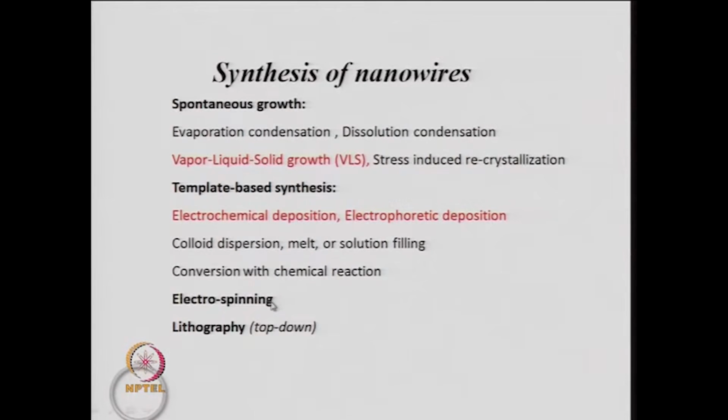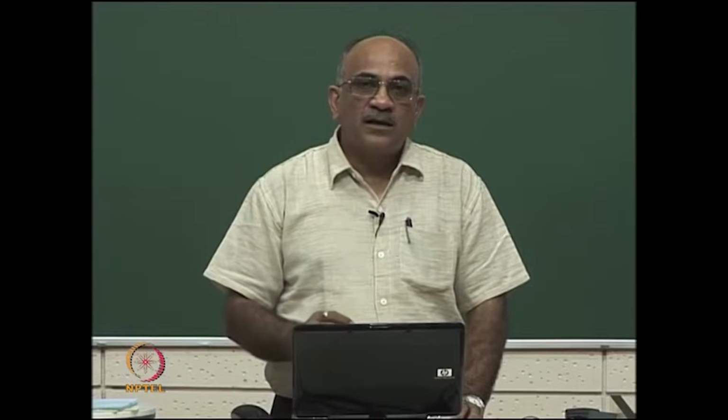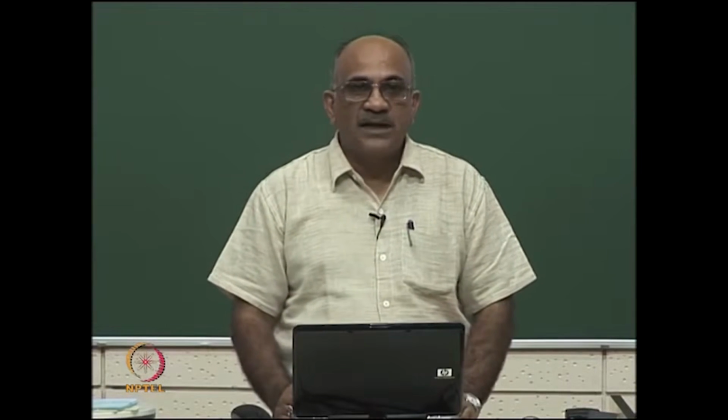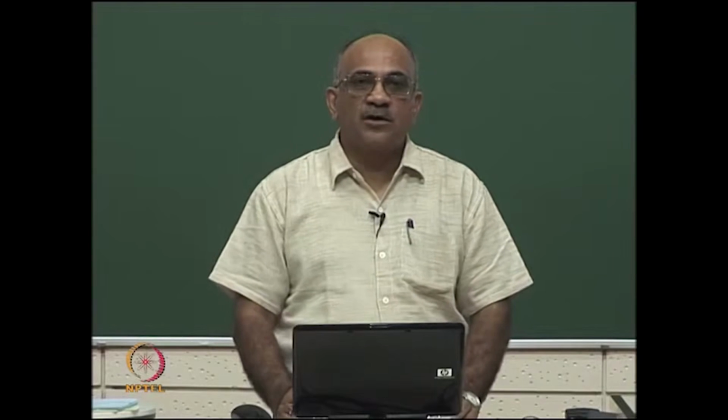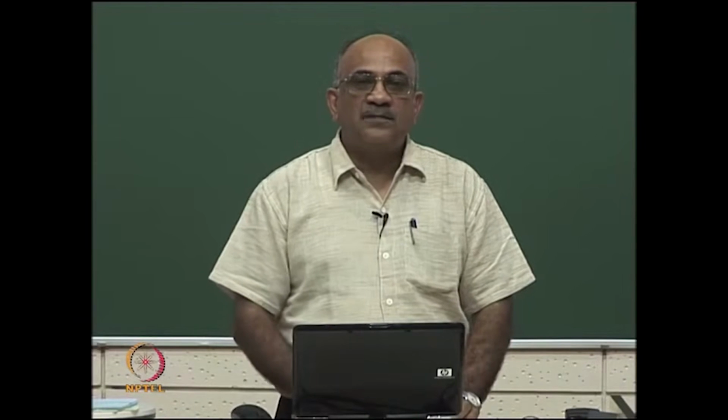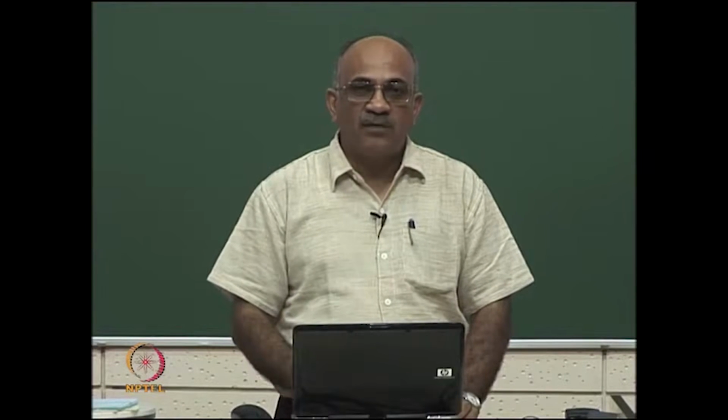There are other techniques which we have not discussed in much greater detail, like colloid dispersion or electrospinning, and there are of course many techniques of making nanowires using the top down approach, that is taking a big chunk of material and then slowly removing material from it using lasers or electron beams or ion beams, such that ultimately you get fine wires.